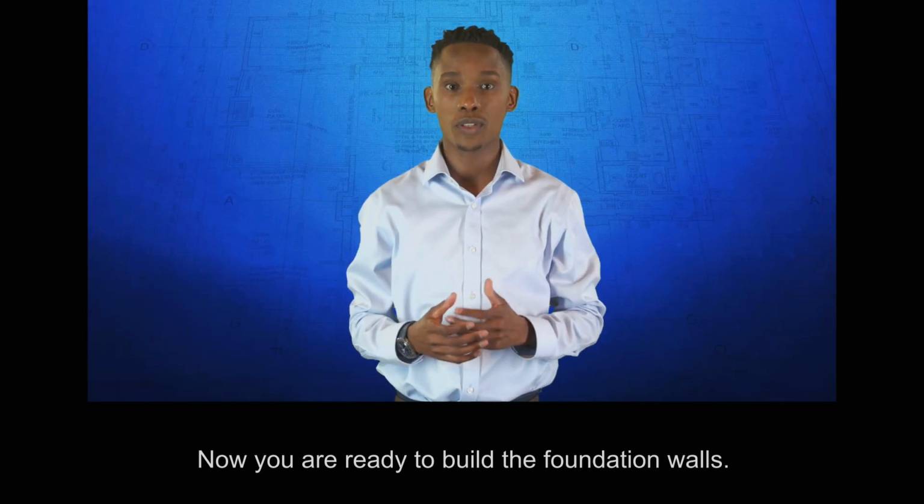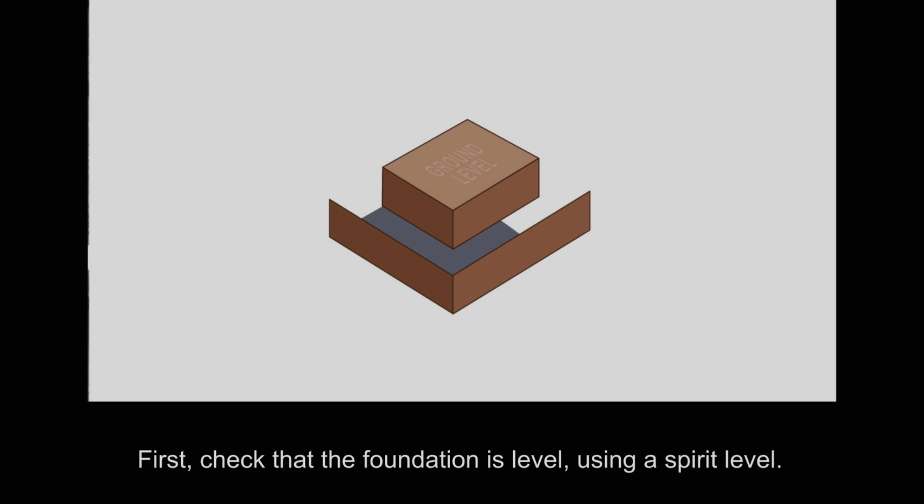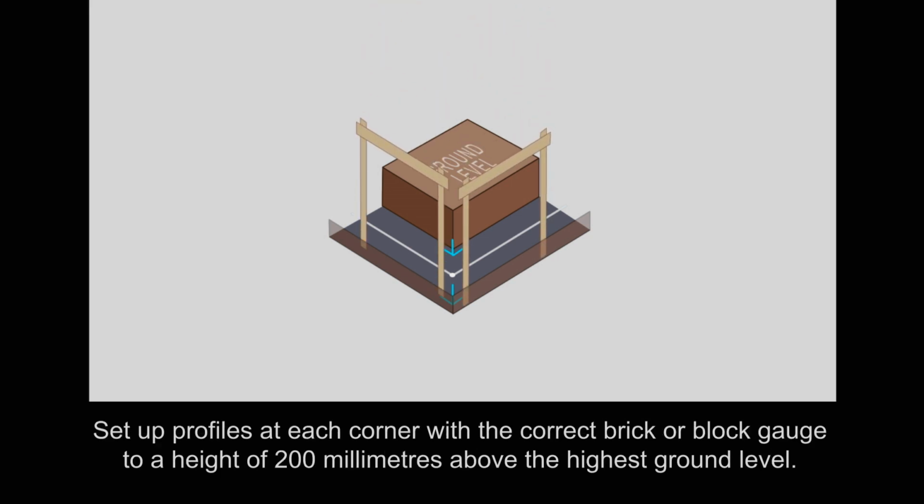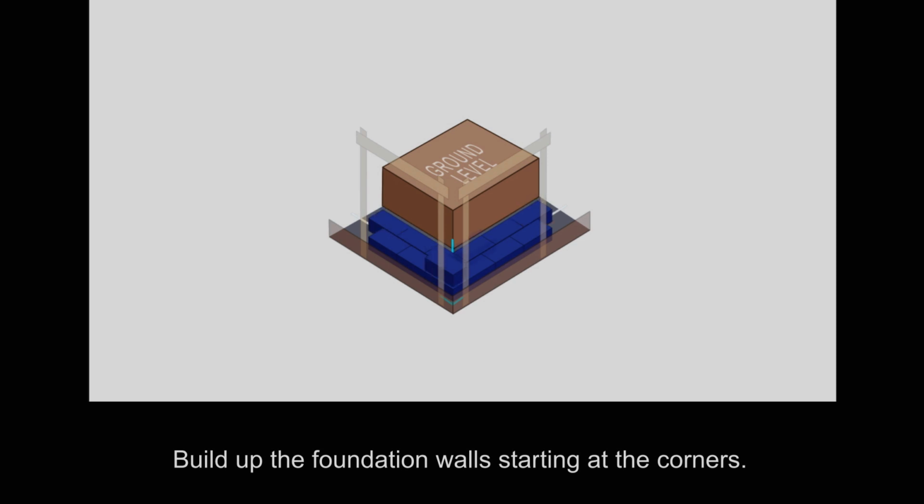Now you are ready to build the foundation walls. First, check the foundation is level using a spirit level. Mark the position of the wall onto the foundation concrete. Mark a point and then draw a chalk line across the foundation. Set up profiles at each corner with the correct brick or block gauge to a height of 200 millimeters above the highest ground level.